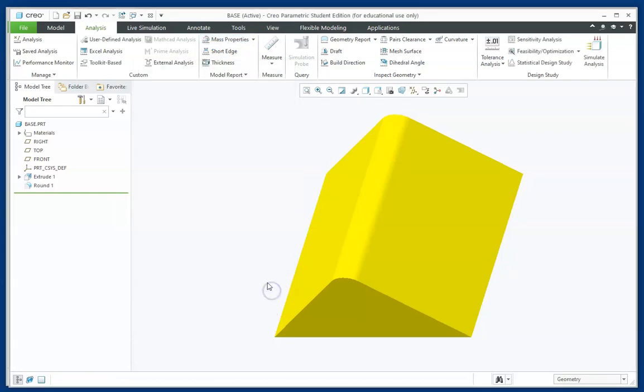One advantage of doing the Edit Materials is not only is the right density put in, but also other material properties for further analysis, for example, Young's modulus and some thermal properties. So I encourage you, when possible, to put in the entire material rather than just the density.